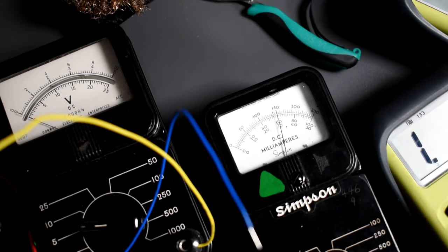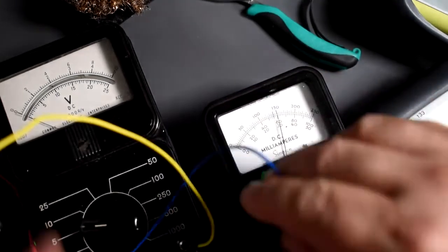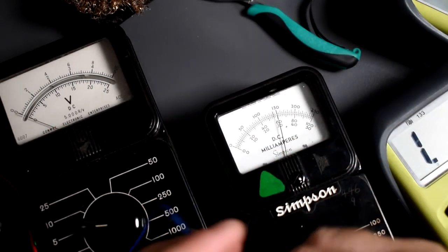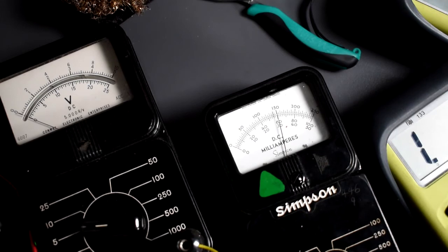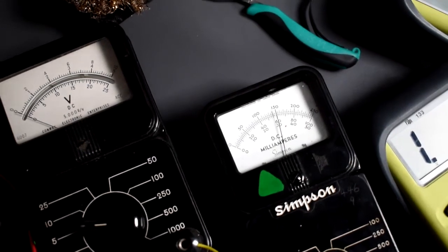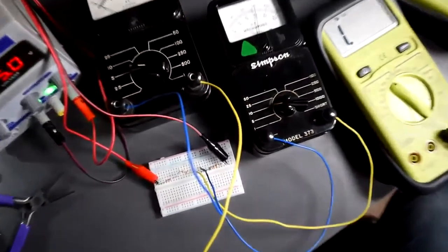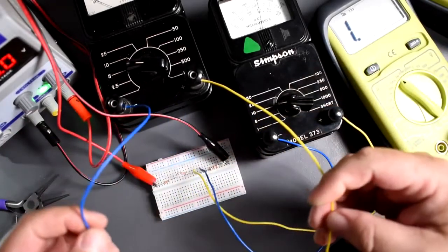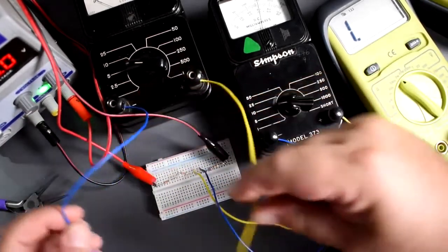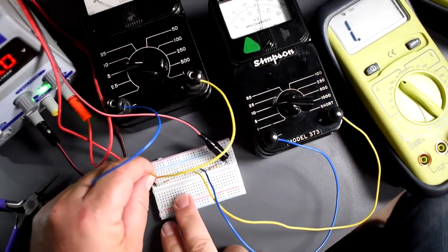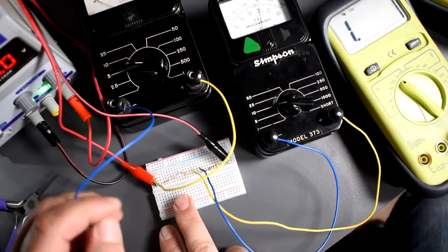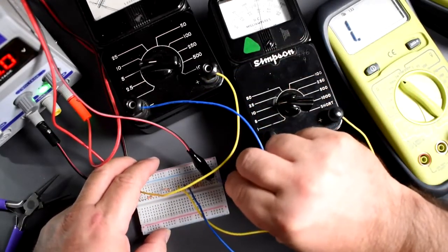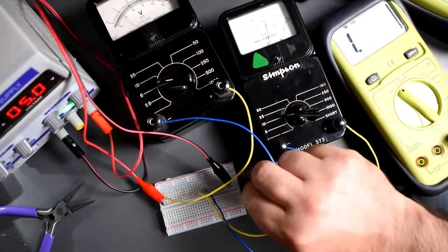Okay. Now we also have a voltmeter here. This one here. And we're going to connect this thing right across the power supply. Right across. So this is where our power supply is applied right here. Okay. So this is our positive, this is our negative, and we're going to connect it right into the terminal here and the other terminal here. I'm just going to touch it a little bit just to make sure that the polarity is okay.